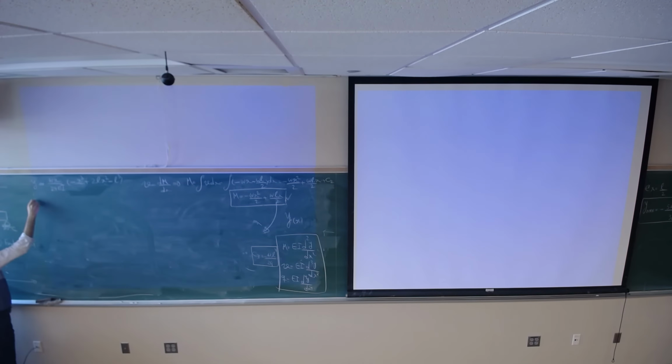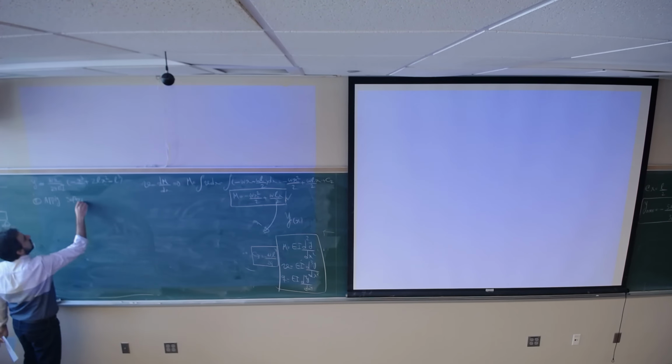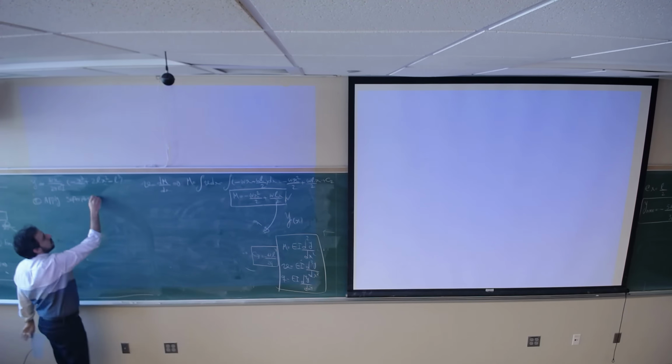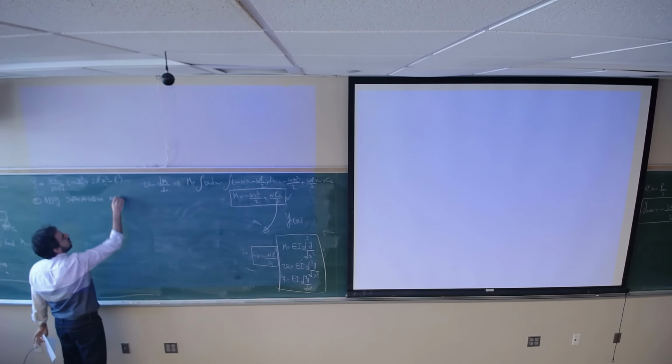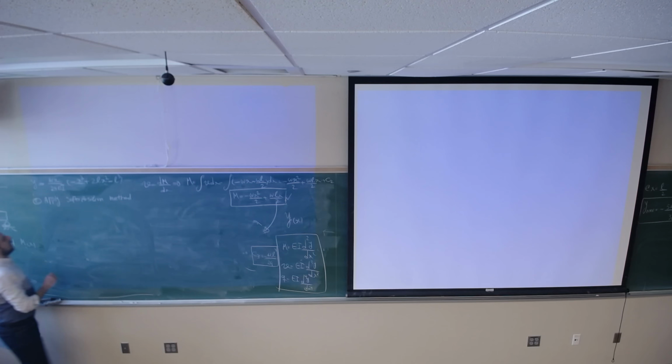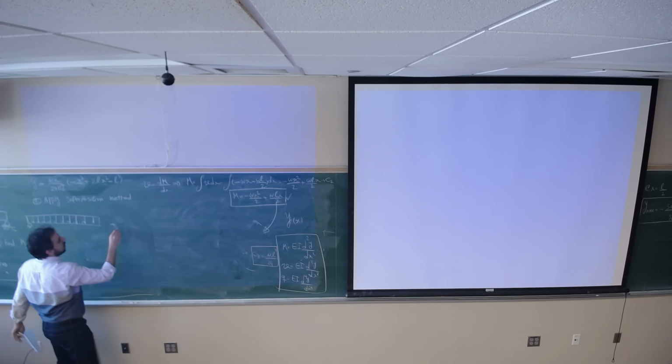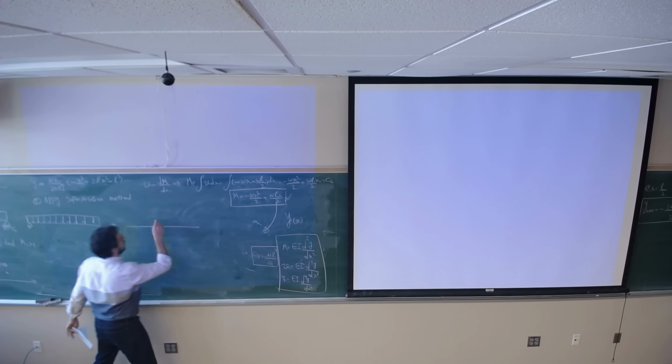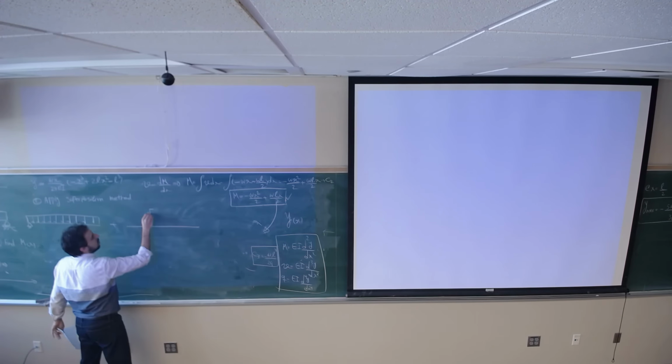But the second approach is to apply superposition. Just break this beam into two beams: one beam with distributed load plus one beam with concentrated load.